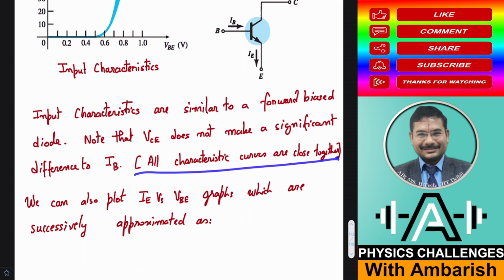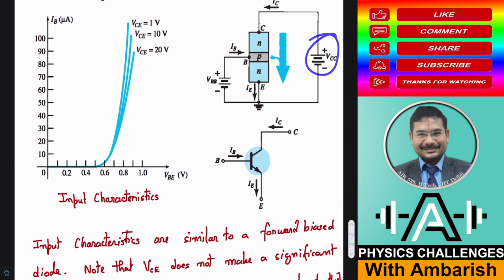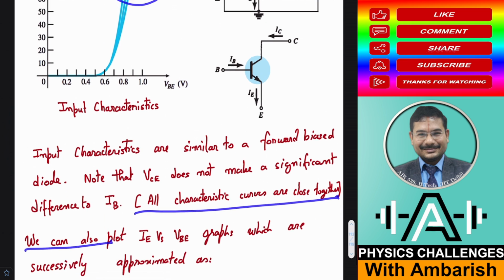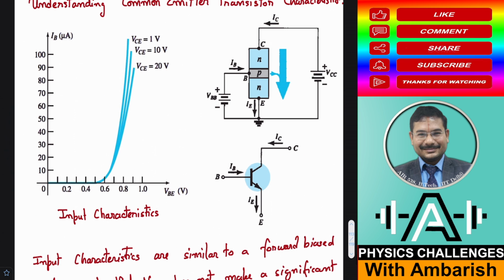All characteristic curves are close together. We can also plot emitter current versus base-emitter voltage graphs, which are successfully approximated as follows. You realize here the base current is in microamperes, because most of the electrons will actually cross into the collector.